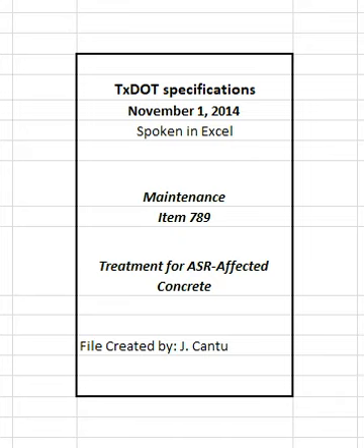2.2 Silicone-based topcoat. Provide silicone resin emulsion paint, SREP, meeting the requirements of DMS 8141, paint, silicone resin for concrete. Match color of coating with Federal Standard 595C color 35630, concrete gray, unless otherwise shown on the plans.